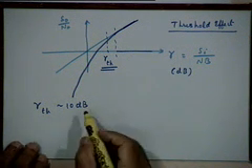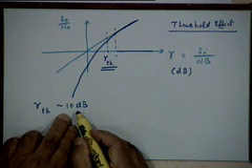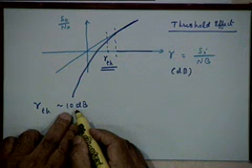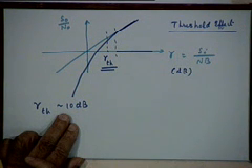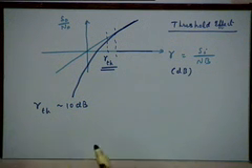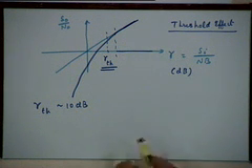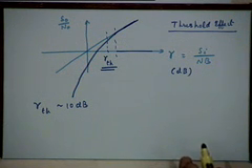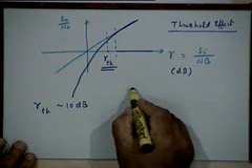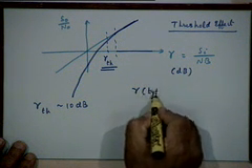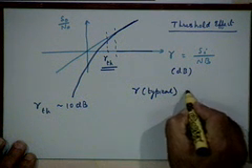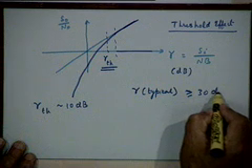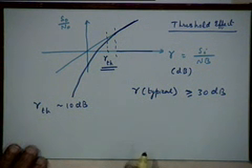That means unless my input signal to noise ratio falls below 10 dB, I will continue to be more or less on this linear curve. And typical acceptable values of the signal to noise ratio in broadcast applications is anyway much larger. Typically, gamma, if you remember I discussed this earlier with you, will be greater than 30 dB or like 40 dB.